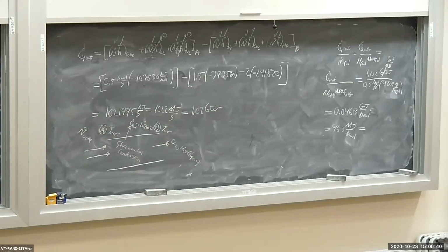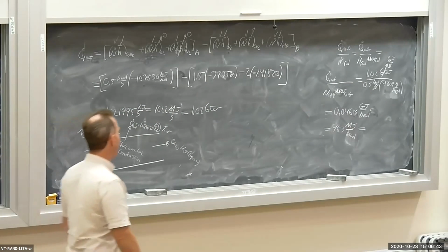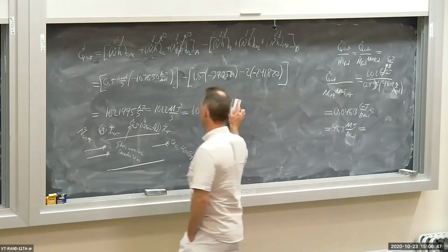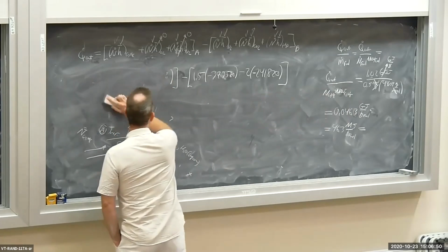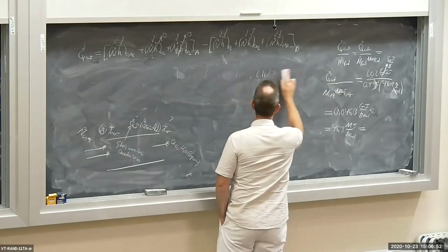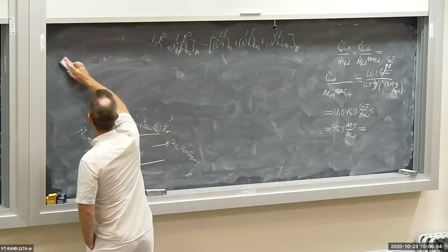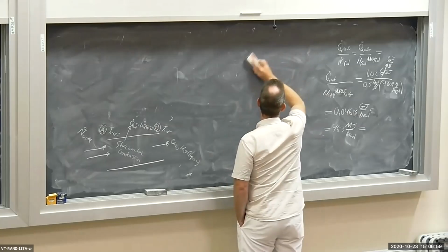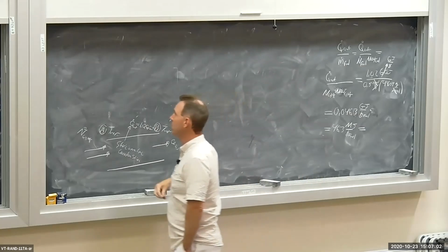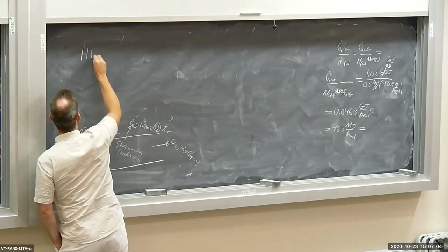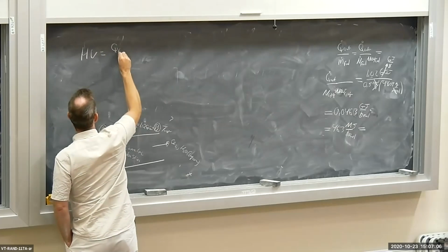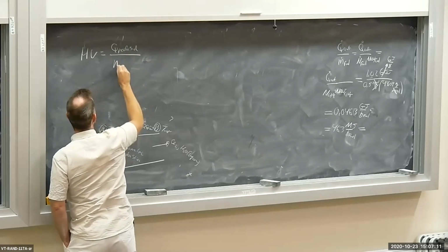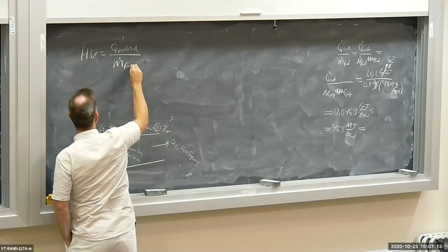This quantity here, Q dot out divided by the flow rate for the fuel, is called the heating value. It's called the heating value of the fuel. It's the total heat released, or total potential for heat release due to the burning of the fuel. Heating value equals heat released divided by m dot for the fuel.